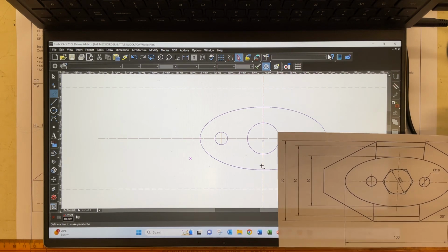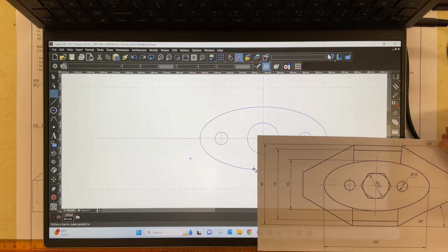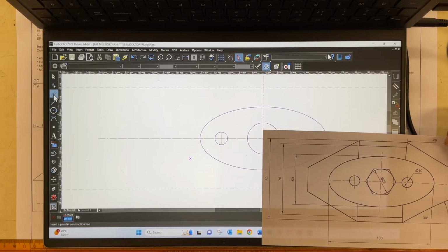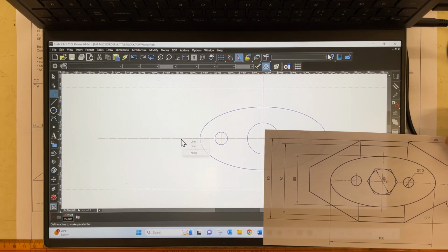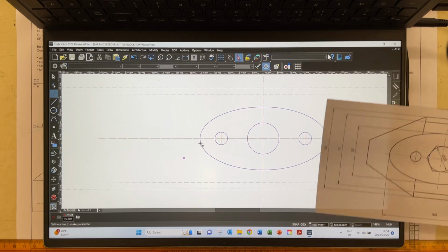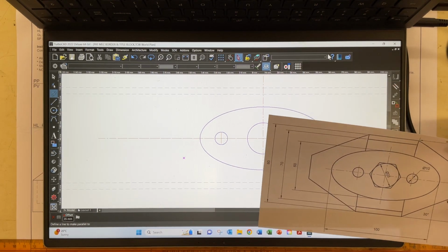Go to this line over here, there, and there's 40 down, 40 up, and there, coming down, there's 40 down. Right, once I've got that in place, it then says 70 over there, so I'm going to do that as well. Go tab 35, enter, go from there, line up, there, line down, there we go. Right, once I've got that, I've got my construction lines in place.